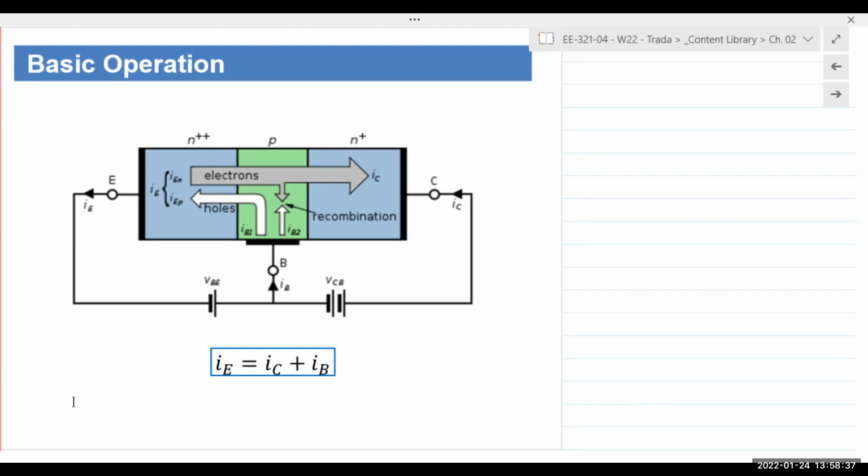Electrons, right? And you apply a positive bias here. What happens to the electrons? They're going to cross over the junction because they're forward biased. At the same time, you have holes here that are going over here, because in P-type material, majority carriers are holes. You have current going this way, bipolar current flow because of both carriers.